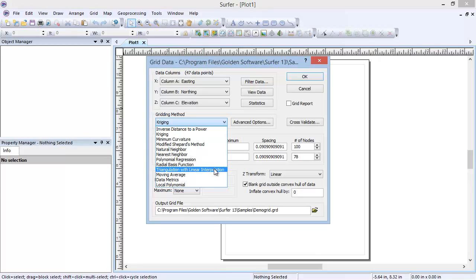methods. If you look at the map produced with the kriging gridding method, but wish to include a fault file containing fault traces, then minimum curvature might be the best option for you. If your data is already on a regularly spaced grid, you might want to try the nearest neighbor gridding method, setting the grid spacing to be the same as the spacing of your data points.